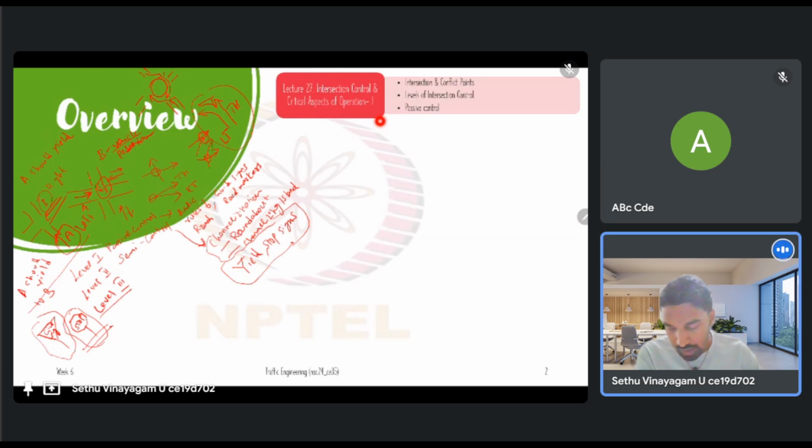In level 3, we can have signalized intersections. In a signalized intersection, we provide traffic signals, where we change the right of way by using the traffic signal. Instead of the basic rules of the road, where we said left must always yield to the right, we are trying to change that explicitly using these control devices.